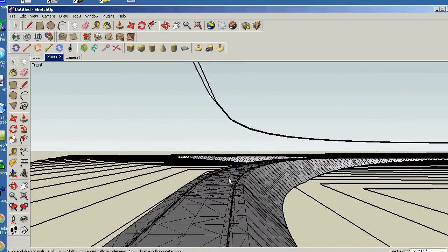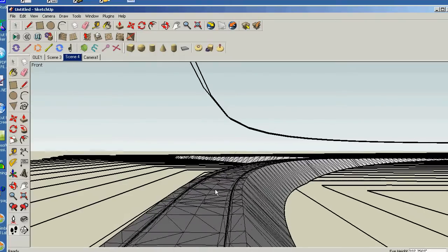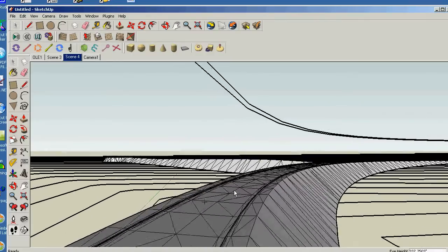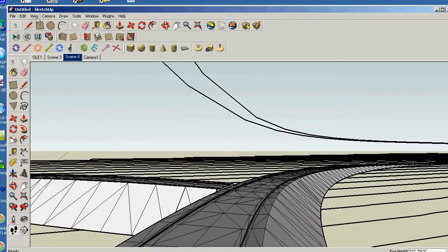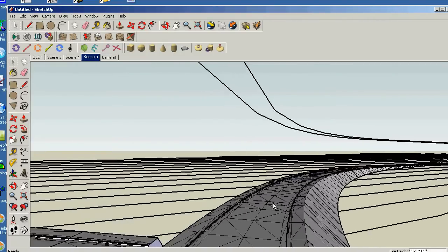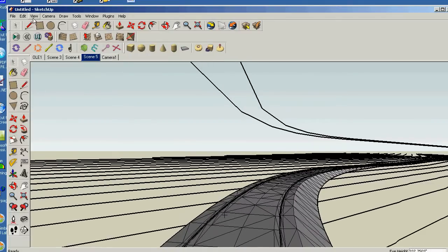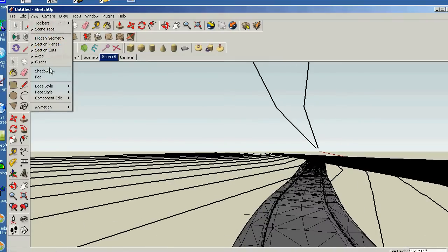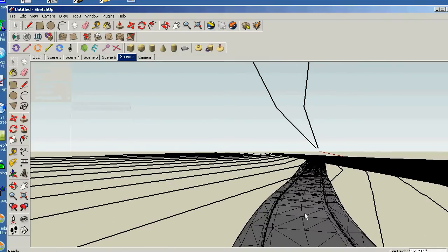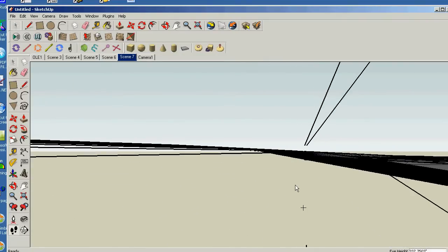And right here, I'm going to go ahead and hit View, Animation, Add Scene. And I'll keep walking around. You start to see where, oh, there's the Cul De Sac. View, Animation, Add Scene. But because when you're going around a curve, you need to take a lot more points. View, Animation, Add Scene. You need to grab many, many more points going around a curve than you would on a straight road. And then going down here, I fall off the road.